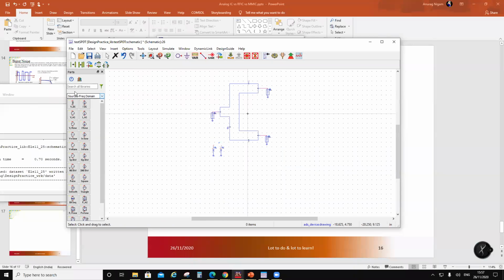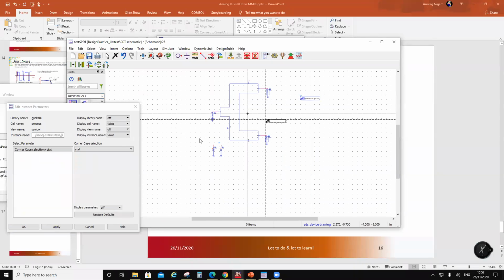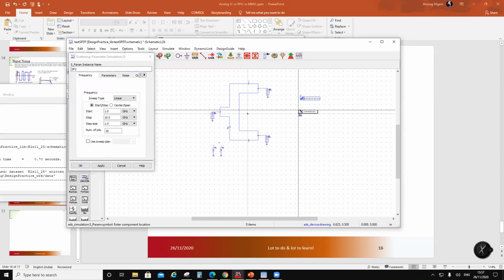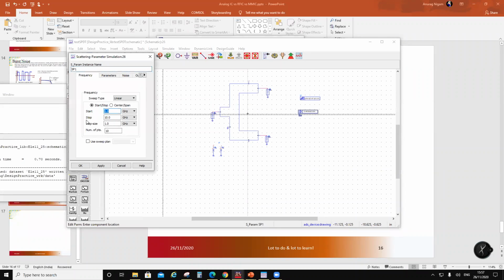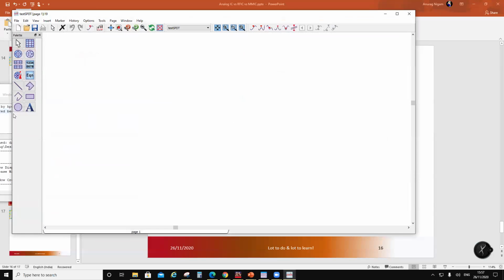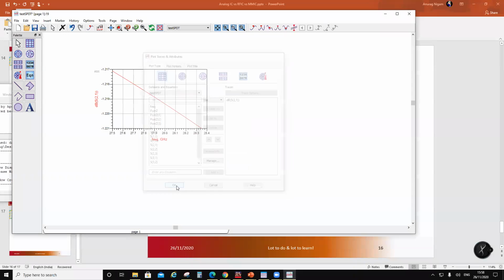Done. So now I'm going to do the S parameter simulation. So I would first here put include file, and then I would put a simulation S parameter. And S parameter simulation here, my band of interest is 27.5 to 28.35. And I'm going to take step of 10 megahertz. Say OK, and I'm going to hit simulate. Then I'm going to look at S21. This is my through path. Okay, so I'm seeing 1.2 dB insertion loss.